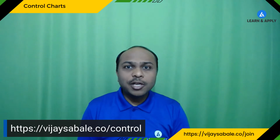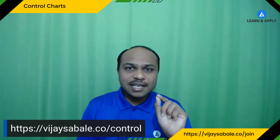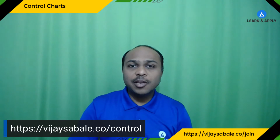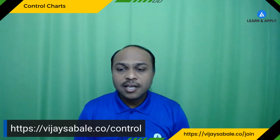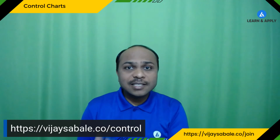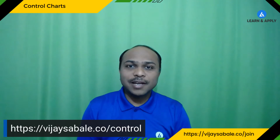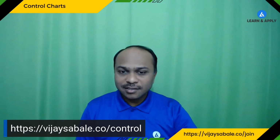For example, let's say in the example that I have explained, every 30 minutes we are going to collect 3 data points, right? So these three data points will be plotted on the control chart as a single data point or single dot. Now, how are we doing that? We are taking the average of all these three data points and using it to plot the control chart. So here we can see the data is collected in subgroups and has a subgroup size of 3 in our example. Is this clear, Akash?